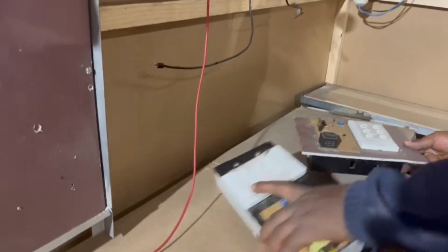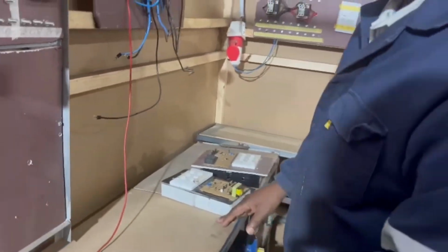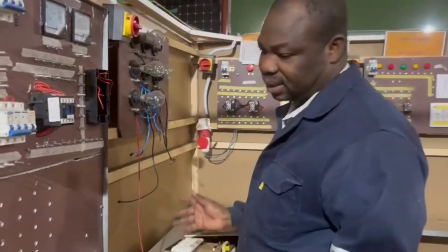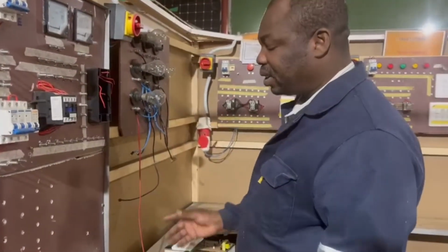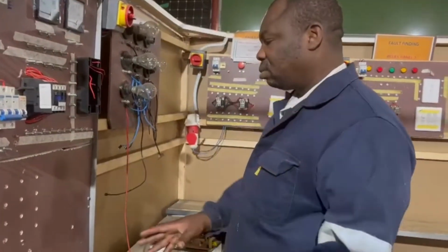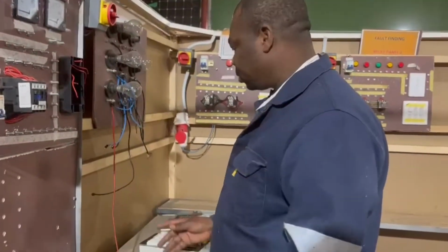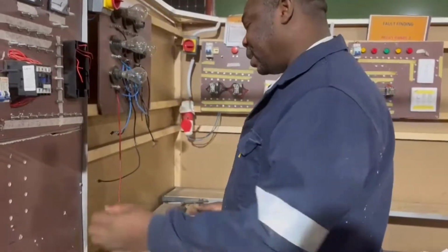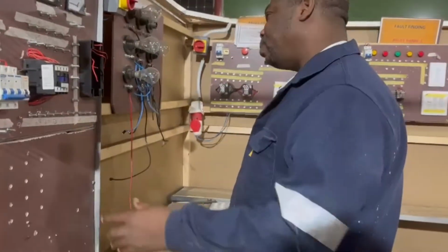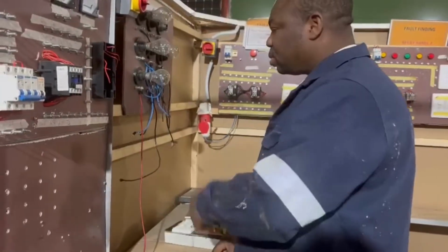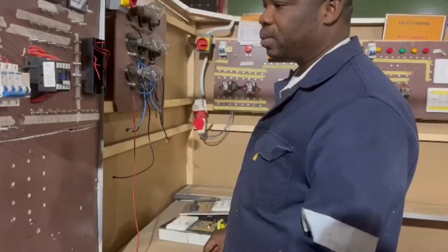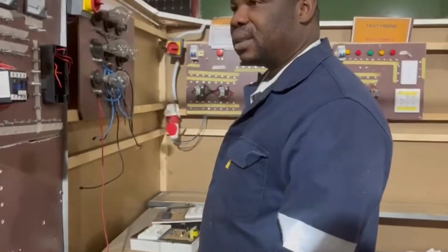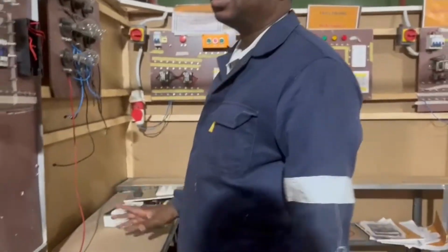The second part is where you'll be given a circuit diagram, and you'll be asked to construct a power circuit. Before the construction, you need to do your layout. After your construction, you have to test your work with a multimeter. You need to measure the AC in and the DC out with the multimeter and also with your oscilloscope. Then you have to compare your answers on both sides. And then maybe you have to do some graph also.